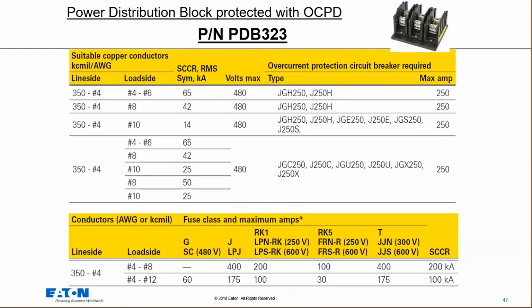All right, and then someone asked us, terminal blocks between the motor starter and the load, UL 1059 type. Should they be analyzed in the SCCR calculations? Yes. Any component that's in the power circuit has to be analyzed, including the terminal blocks at the bottom of your panels, guys. Just be aware that you've got terminal blocks at the bottom of your panel for bringing in your equipment from outside. That's in your cabinet, and you now need to take those into consideration. So just be aware those are another gotcha.